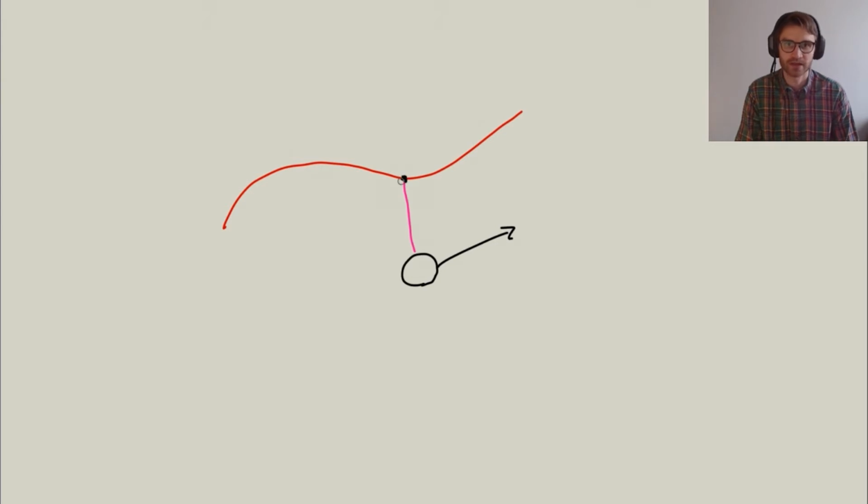Now, rather than looking at this point right next to the turtlebot, we're going to look ahead forward in a distance that is predefined. So this is a constant distance. So we walk in this path the length of look ahead, and then we end up in a point that is in the future in the track, not right next to the turtlebot, but in the future.